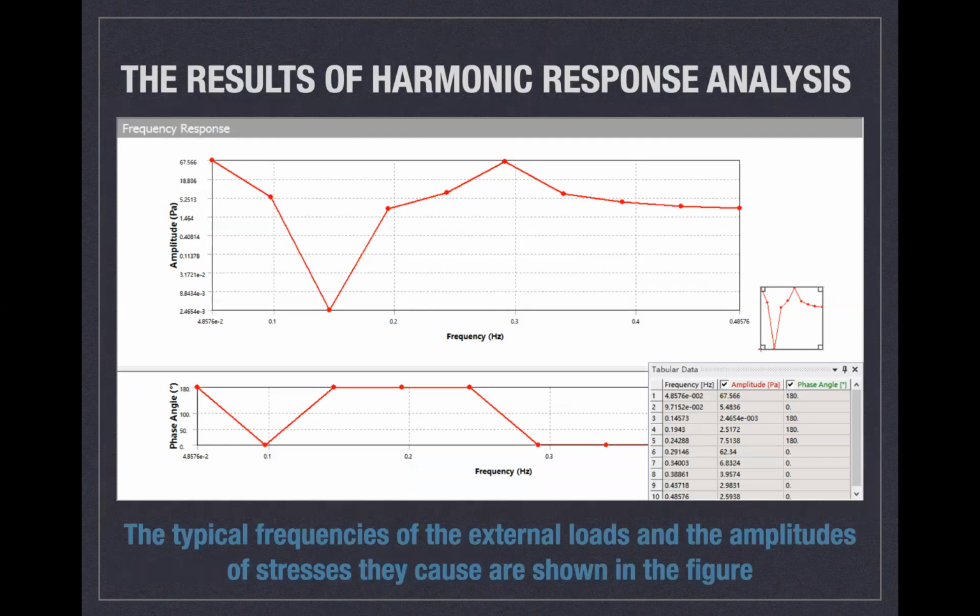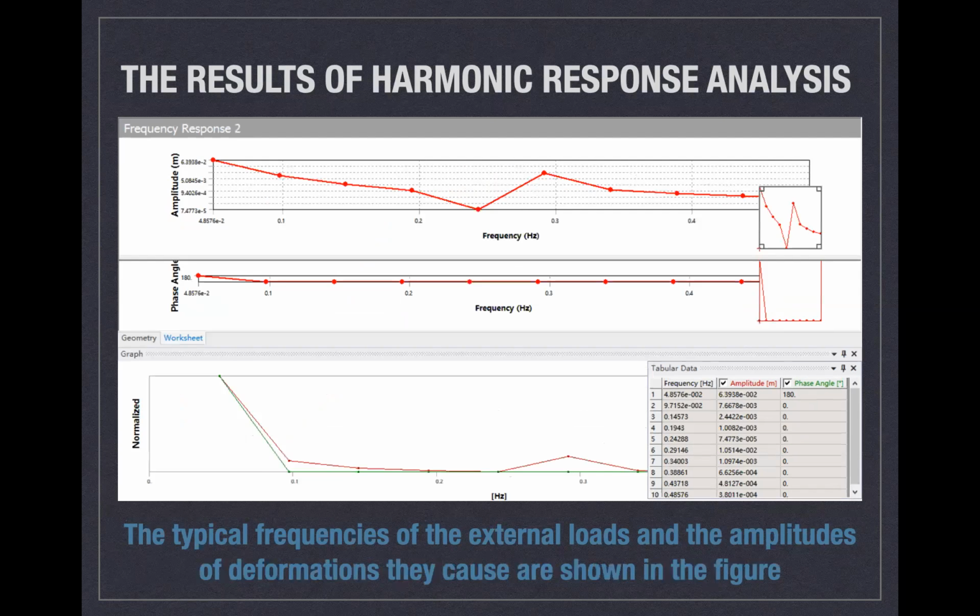And this is the result of the harmonic response analysis. The typical frequencies of the external loads and the amplitude of stress they cause are shown in the figure. We can see in the picture that at some certain frequencies, the amplitude of the stress is much larger than at other frequencies. So at these frequencies, the structure can become unsteady and very dangerous.